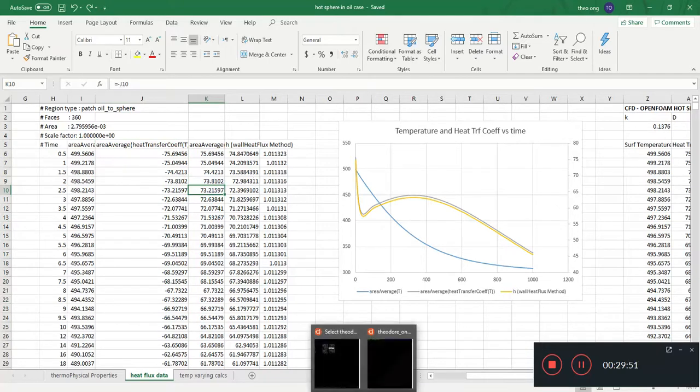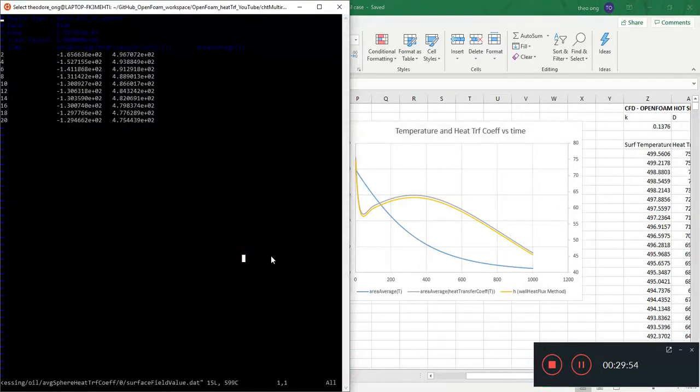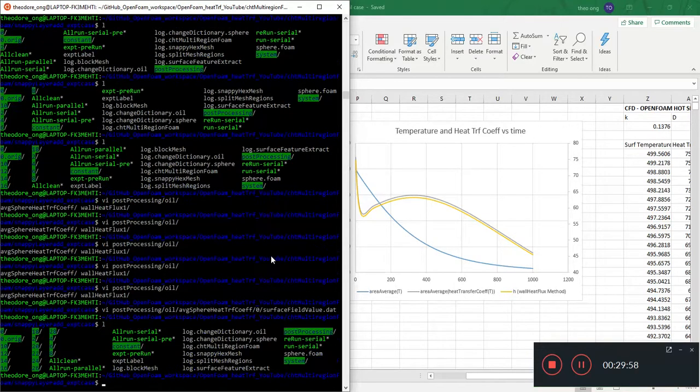So I'm just gonna let this thing run. Yeah. So at least for this demonstration, it shows you that making your boundary layers for your sphere for this natural convection case does make the results better. I mean, for the Nusselt number, it matches the correlation better. So this is something we need to be very mindful of, especially the mesh near the boundary layer.